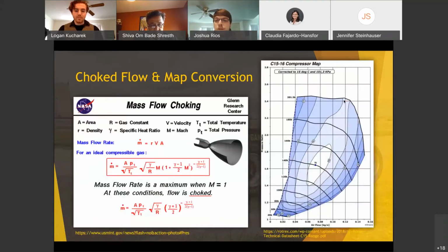Next, it is very important to understand the behavior of the airflow through the restrictor. Since there must be an intake restrictor fitted to the vehicle, we can calculate the maximum amount of air that can flow through the restrictor, and thus the maximum amount of air that can be ingested by the engine.